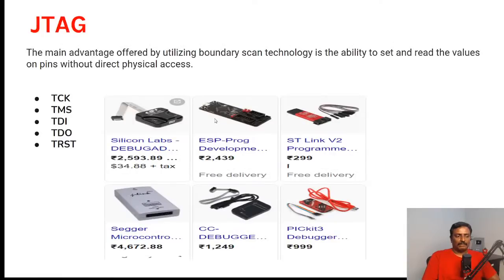Coming to JTAG, Joint Test Action Group: you have TCK, the JTAG clock, TMS, JTAG mode select, TDI, JTAG input, TDO, JTAG output, and JTAG reset. These are all the pins. You need an emulator to program the microcontrollers, and you could do functionality testing with JTAG.